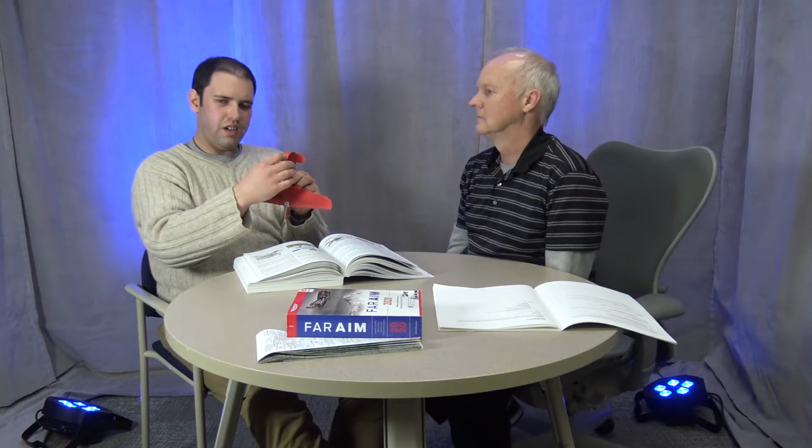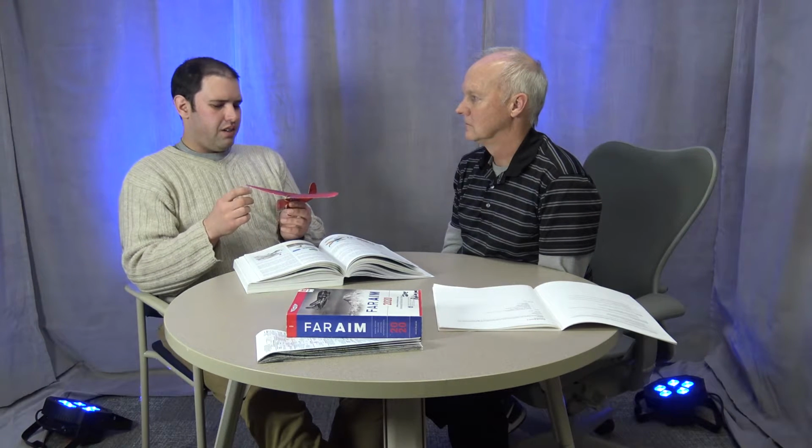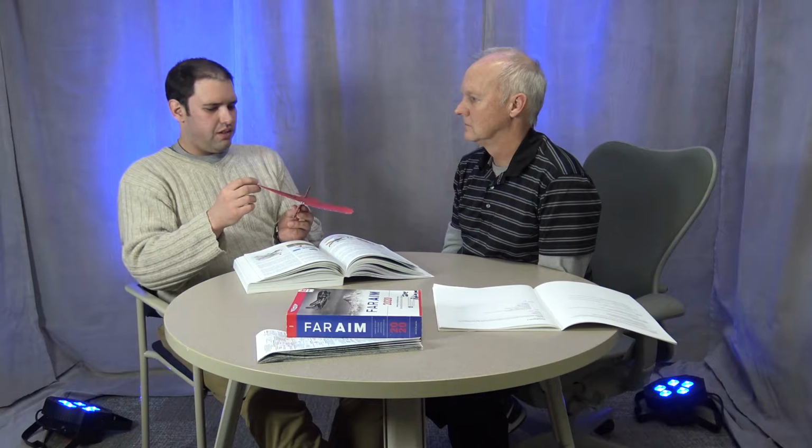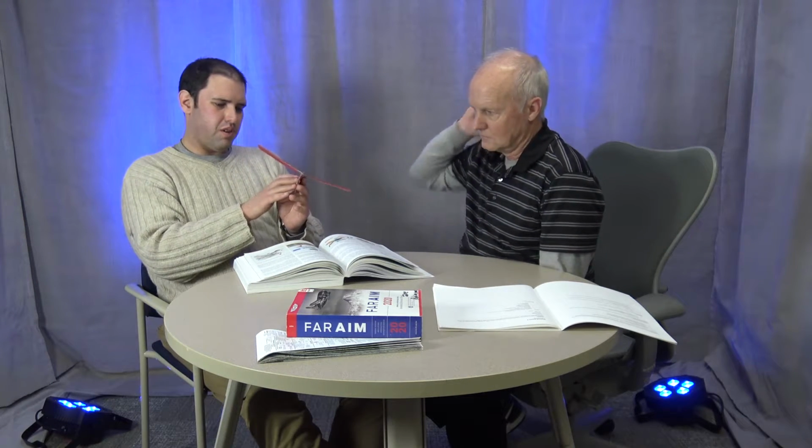And the rudder on the vertical stabilizer back here moves left and right, and what we primarily use it for is just that, counteracting the outside pull of the ailerons in order to keep us flying nice and straight as we enter a turn. Obviously, we also use it to steer on the ground, and we use it to align the airplane with the runway when we're doing a crosswind landing. We'll get into that later.